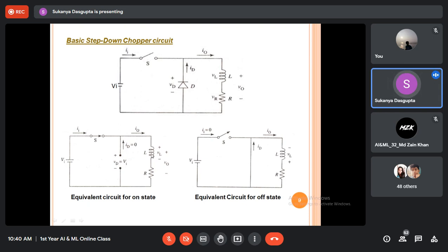It's an inductive load, so inductor will be storing some energy because it's an energy storing element. So whenever current is passing, that means whenever current is rising through this inductor, the voltage will be developed. That means during the transient period, as soon as you close the switch, what will happen? Current starts rising from 0 ampere to say the final steady value, that is, for example, consider I ampere.